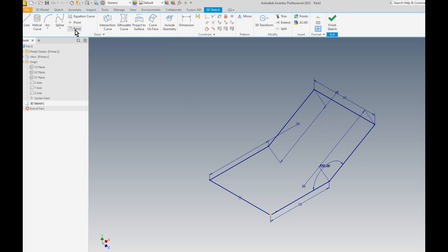So here's bend. Okay, so the bend that we're going to use, I'm going to use 5 millimeters. We can change that. I'm just going to leave it at 5 millimeters. But all I'm going to do is select the edges, and it will put in the 5 millimeter bends, just like that. Okay. Now they're all interlinked.